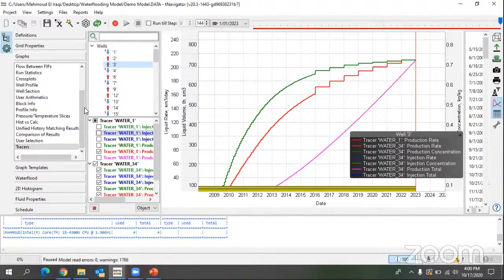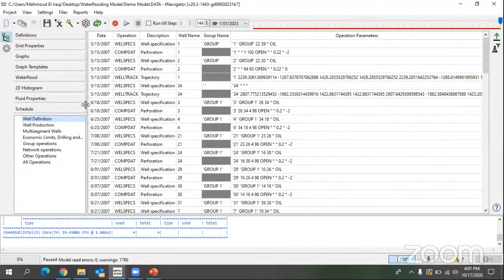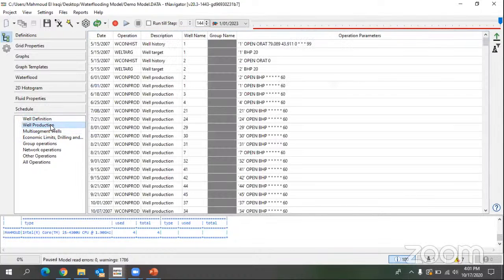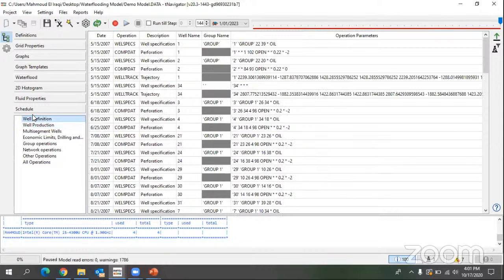As a general process of populating the dynamic model with data, we use production data from our reservoir and populate these tables with data, and also determine some schedule, as we specify at which time there was a step to perforate a well, or to maybe close a well, or maybe turn a well from production into injection, and other operations. Maybe we'll do some hydraulic frac, so we will edit the properties again around this well. Actually, this was an overview of the simulation module.